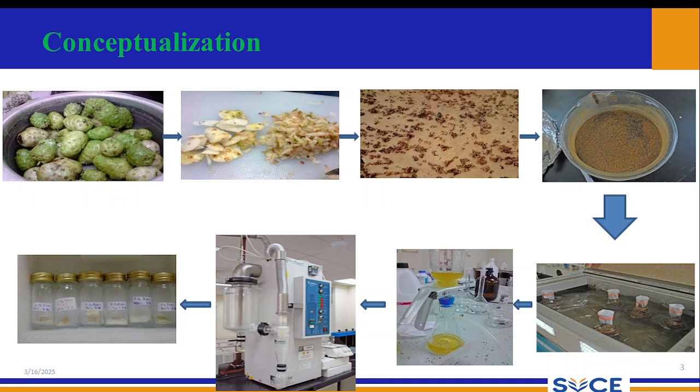Then later, with a pulverizer, I powdered the dried particles and subjected them to hot water bath extraction using a particular solvent, methanol, ethanol, and then you can see the lab experimentation extracted sample. The lab picture is there. The conical flask along with the extracted sample is over there. This extracted sample has been subjected to spray drying and I have obtained the powder.